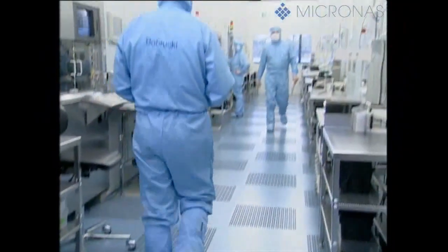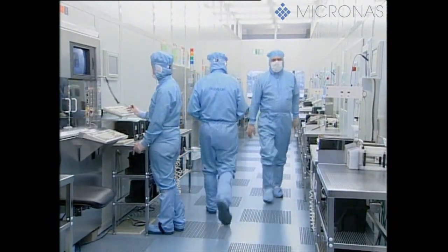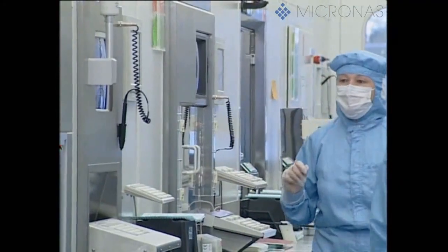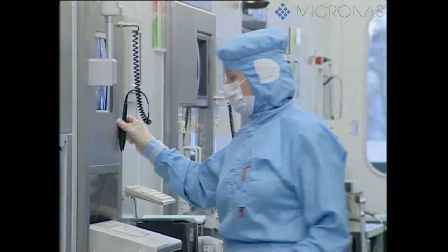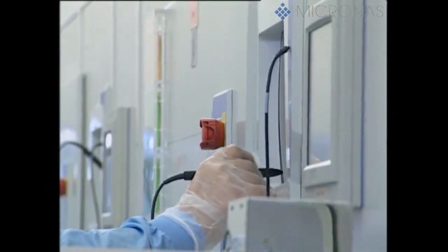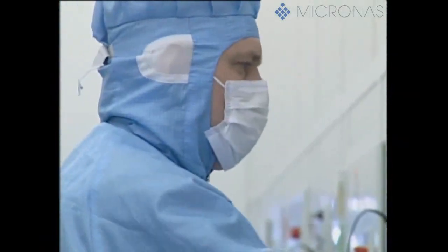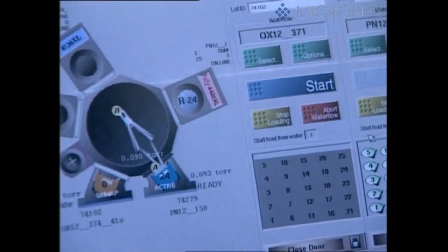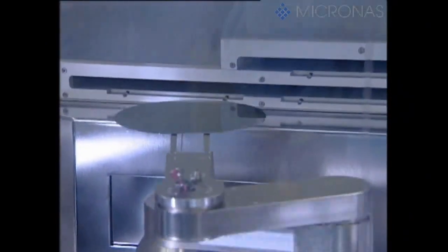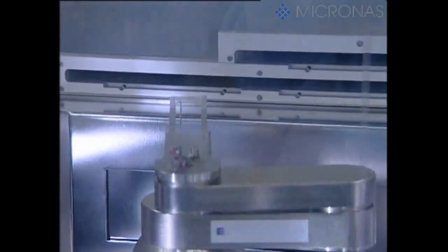During the etching process, the photoresist structures that have been built up are transferred to the layer beneath by means of ionic chemical etching processes. In this way, contact holes are made through insulator layers and conductor structures. After etching, the photoresist is removed, a further quality inspection run through, and the wafer cleaned many times over. The next process can then be oxidation, coating, or an ion implant again.